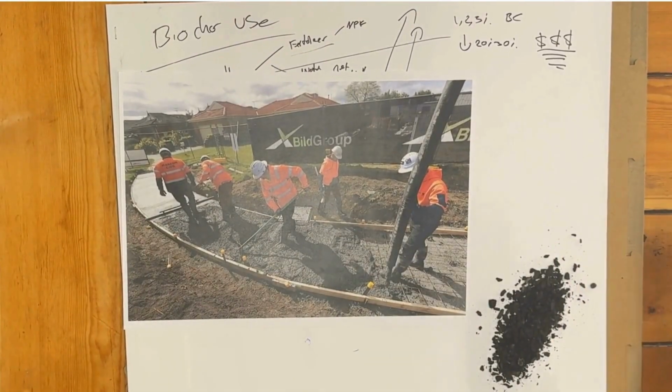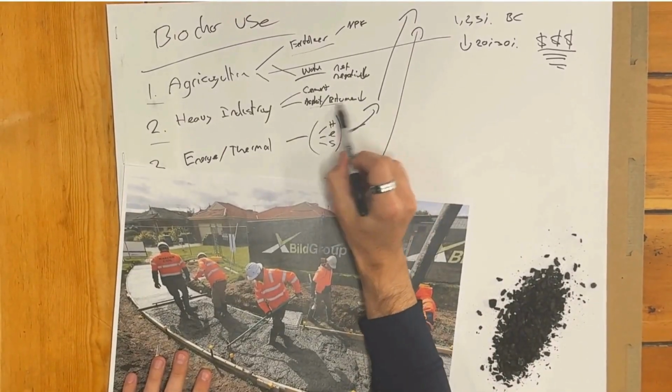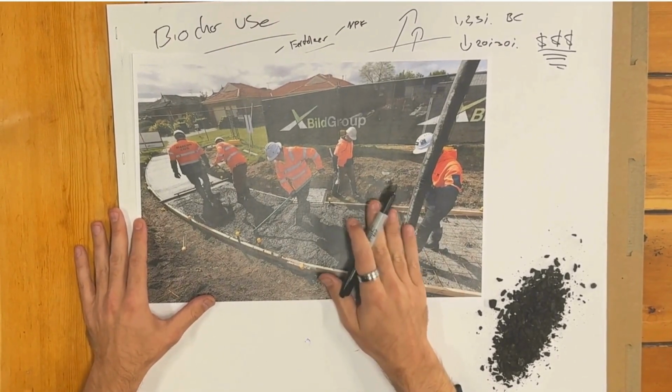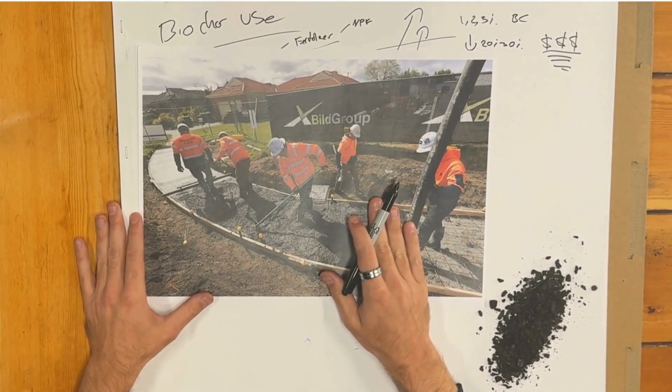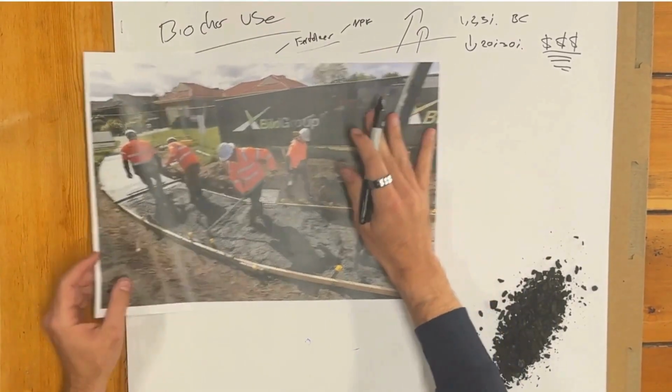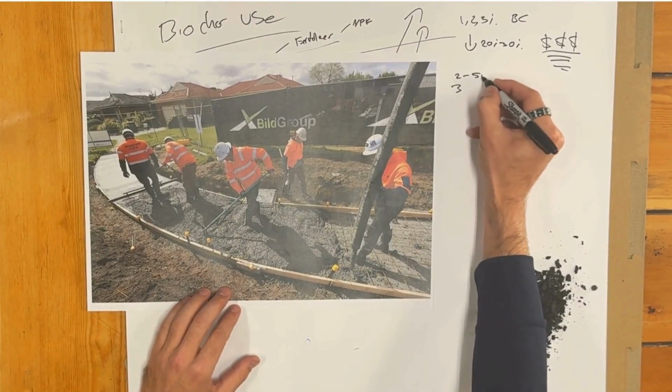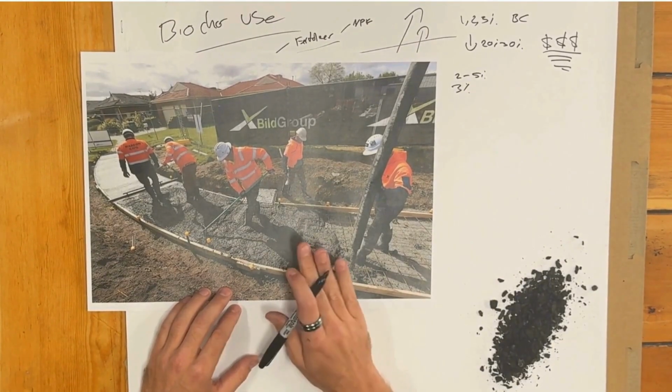Okay, here we're going to talk a little bit about probably more about cement, but there's a lot in bitumen as well. This one was actually in Victoria, Australia, where biochar was blended at 3%. Usually it's recommended to blend about 2 to 5% biochar. This one was 3% into the concrete aggregate, and then just built and run as standard concrete.